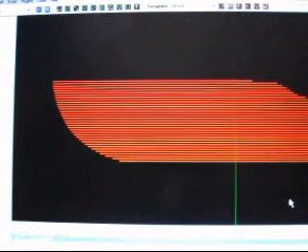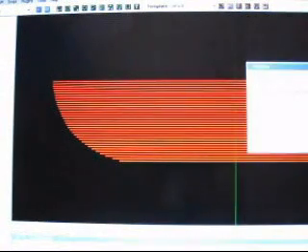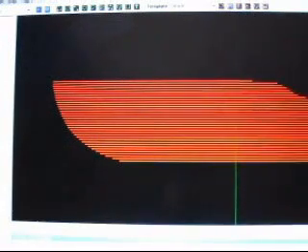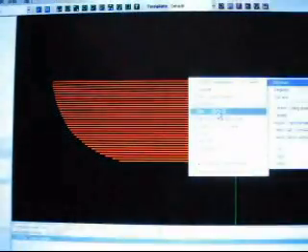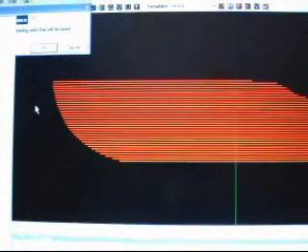So I'm going to hide this layer, show my active layer, and paste them there. Now while they're still selected, I'm going to go polylines, convert to polylines, and then polylines, join. Say OK. So I'm just going to do this a few times, a section at a time, until I get the whole thing converted to polylines and joined.